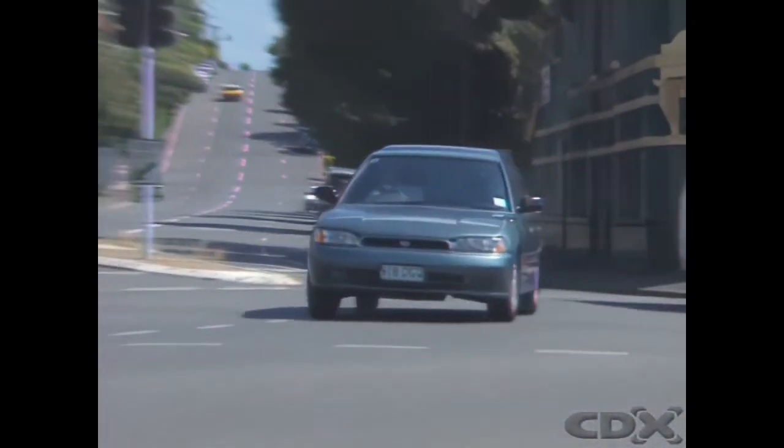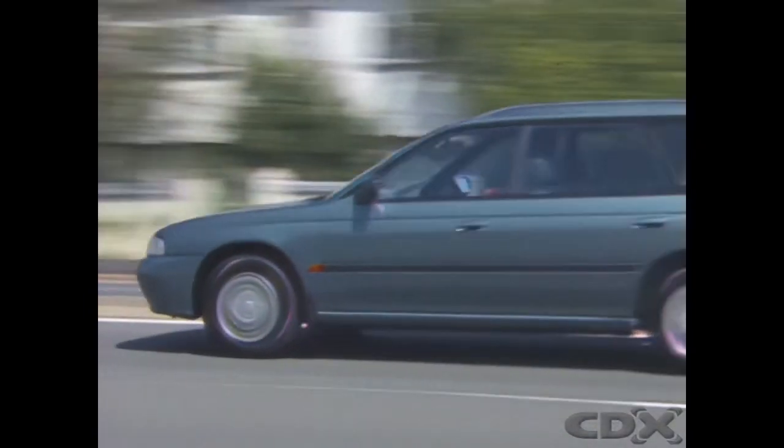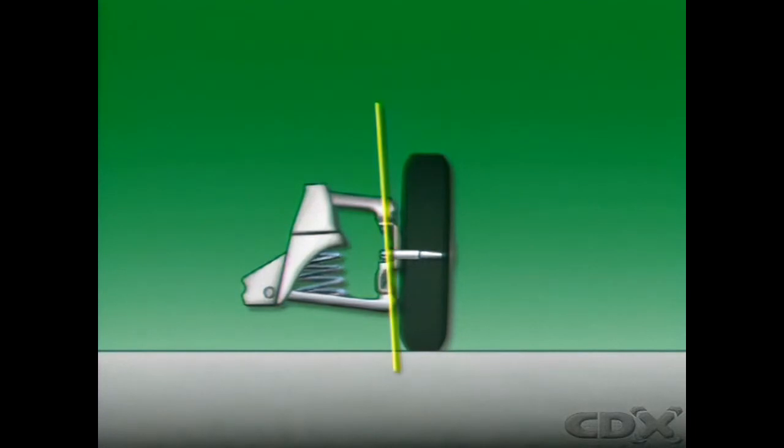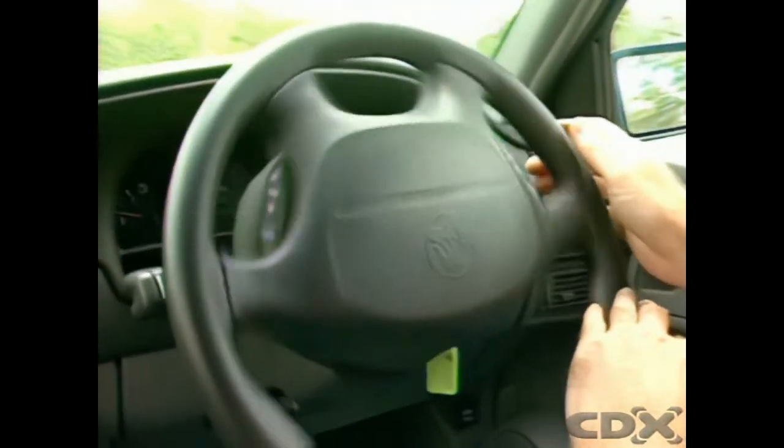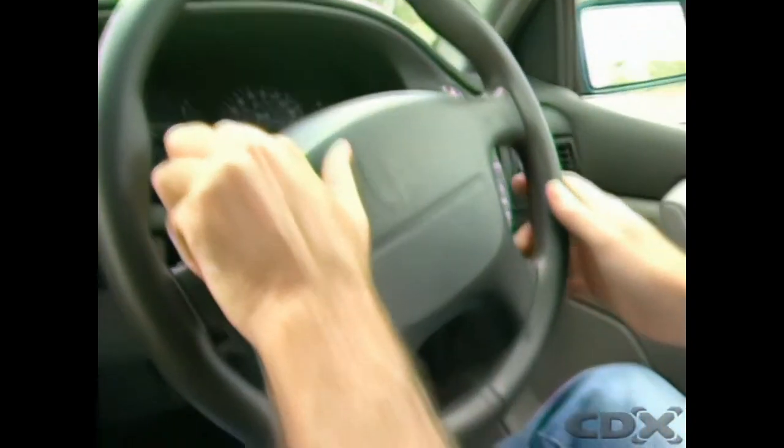The axis around which the wheel assembly swivels as it turns to the right or left is called the steering axis. It is formed by drawing a line through the upper and lower pivot points of the suspension assembly. Seen from the front of the car, it is tilted inward. The angle formed between this line and the vertical provides steering axis inclination angles.